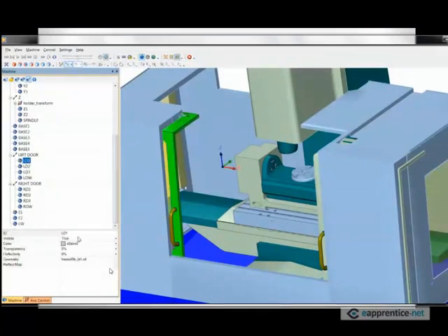Oh, I didn't have all my limits set, but what I need to do is I don't want to see this enclosure and the door all the time. I want to be able to turn it off. So what I'll do is type in MH underscore under the model name, and I have to pick every model that I want to machine hide. That's the command that I'm doing. So every model that I prefix with this MH will be disappearing on just one switch.